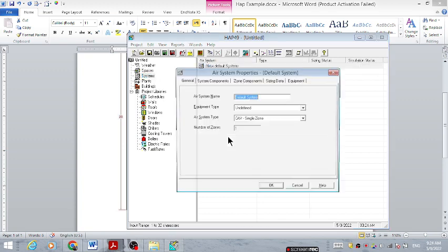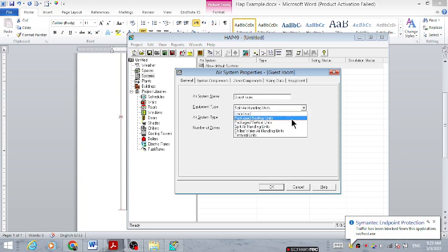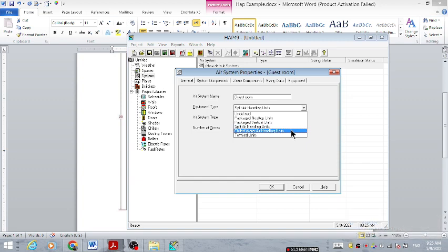System is defined. It's sort of easier from the guest room. What type of system do you need? You need split. Simple. Split air handling, package rooftop, package vertical unit. What type? Chiller? No chiller. Chiller is very big and it's not for one space. So I will prefer split air handling unit. Single zone, CAV, single zone.